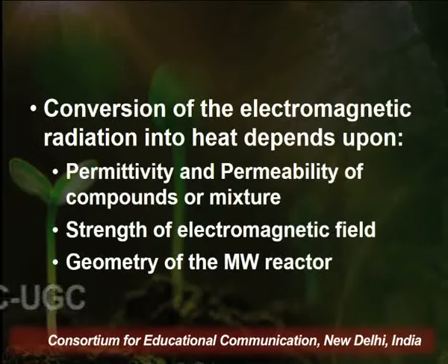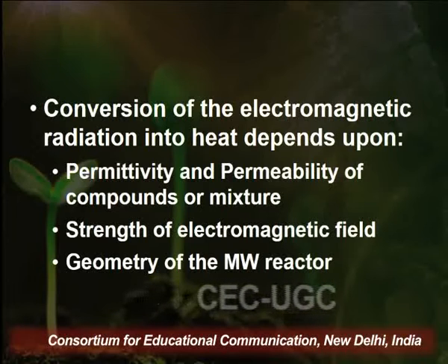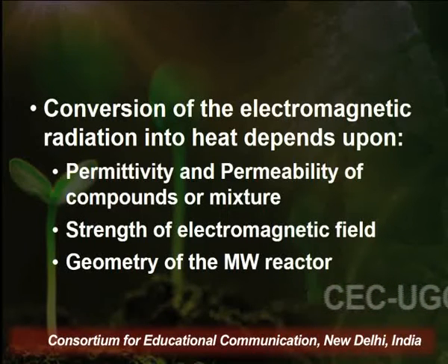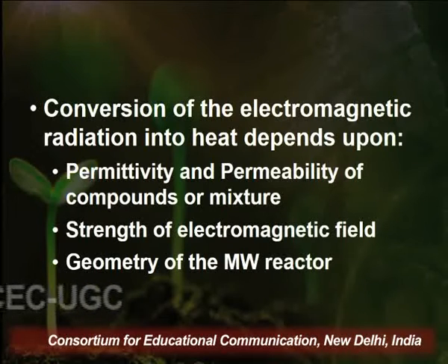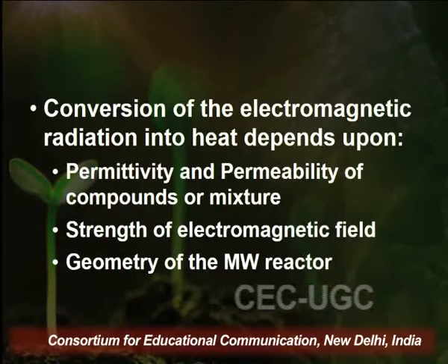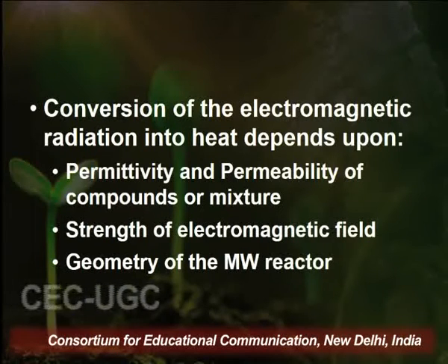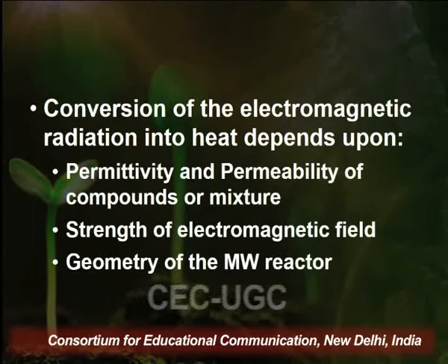Now, as I told you, microwaves have a very small amount of energy, and they largely depend upon the conversion of electromagnetic radiation into heat. This conversion largely depends upon three major factors: permittivity and permeability of the compounds or mixture, strength of the electromagnetic field, and geometry of the microwave reactor or the instrument which we are using.